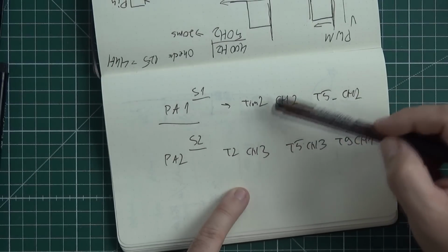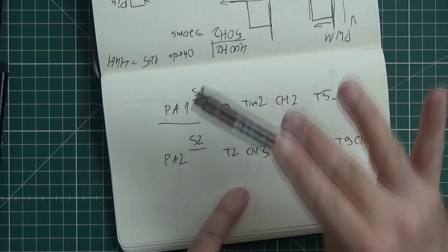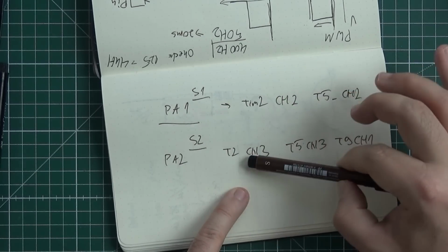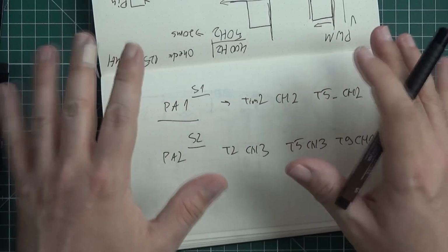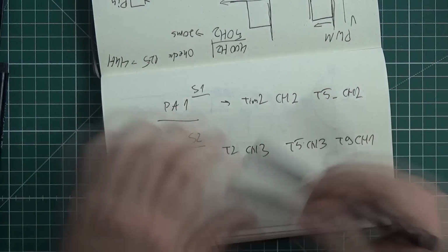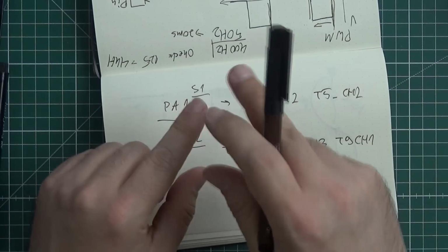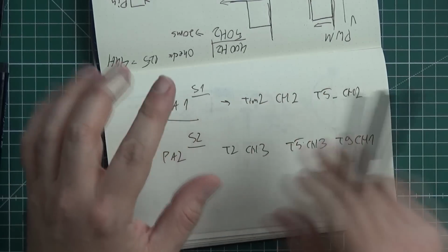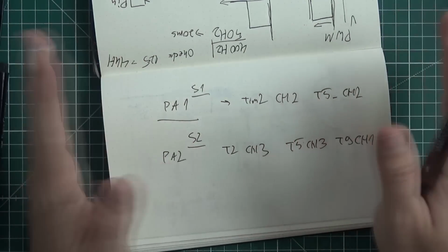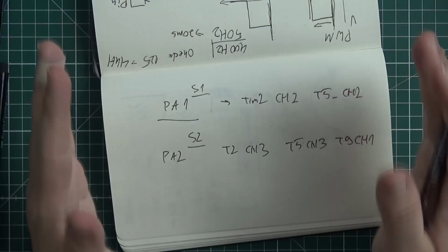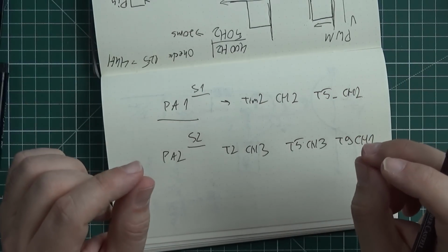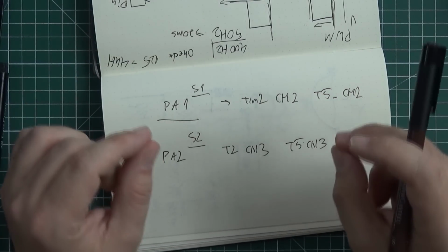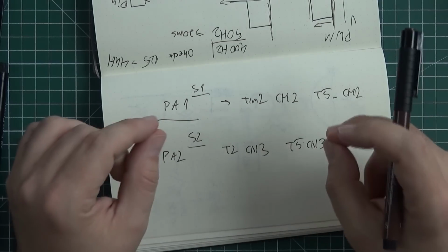Oh, there are channels, because not all, but some timers are divided into channels. The timer still has to have the same frequency, but then using the channel you can decide how fast the value will go down on the timer. It simplifies. You can have multiple pins running the same timer as long as the channels on the timer are different.